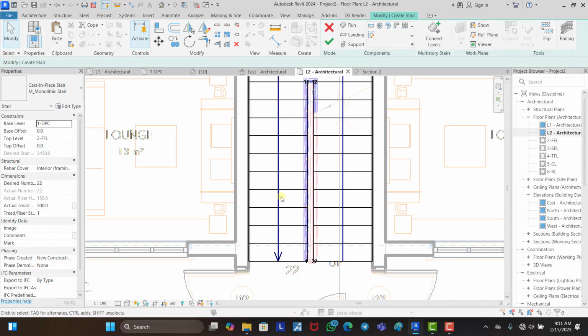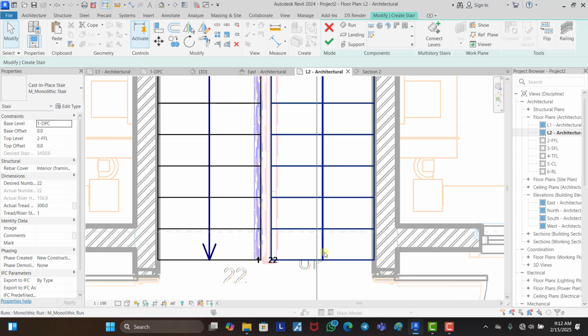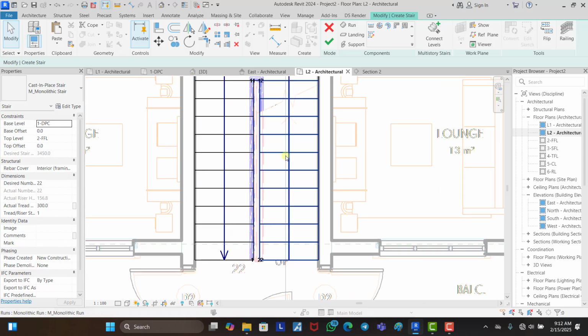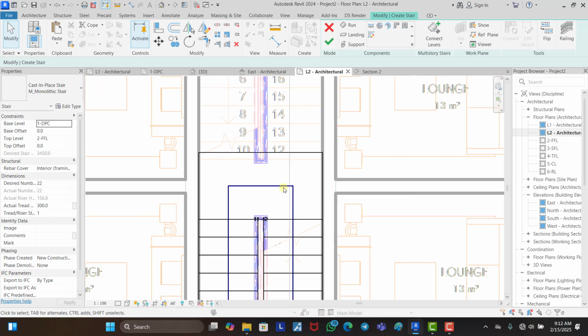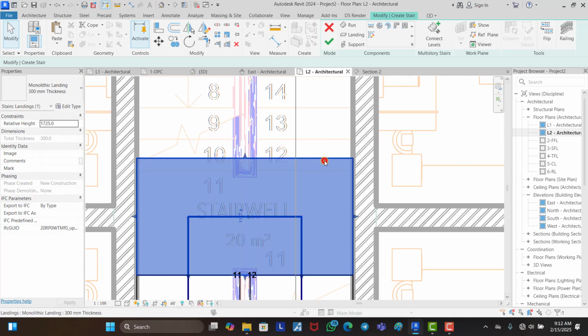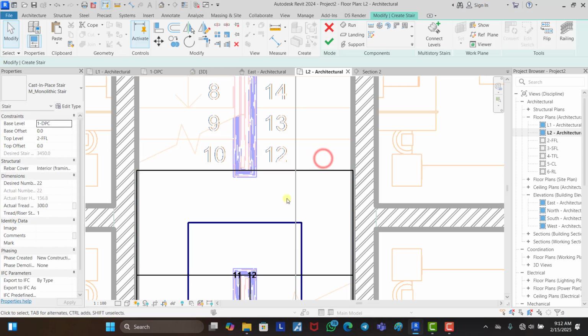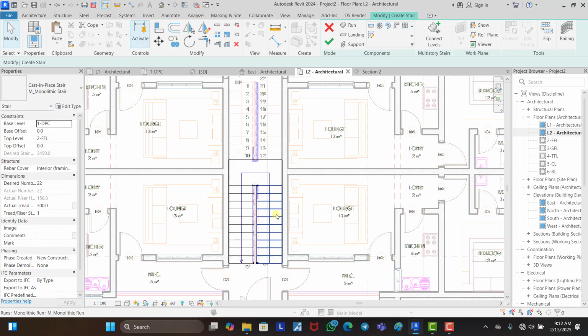So we can then adjust this to this point, adjust this to this. Perfect. All right, so once we are done, the next thing to check, you can see up. This is telling us that the stairs is moving upwards here, and the arrow on the stairs we just drew shows that yes, it's actually moving upwards. Fine. Then the next thing we need to do is to create these other stairs at the back. Now you can see where our landing stopped, so we need to adjust our landing to stop at that same point. Perfect. Good.